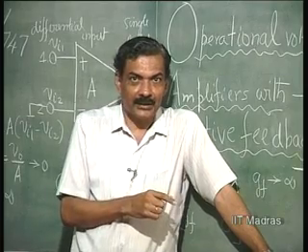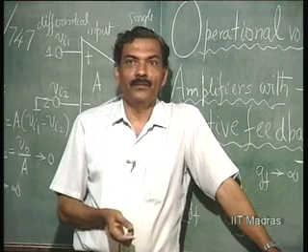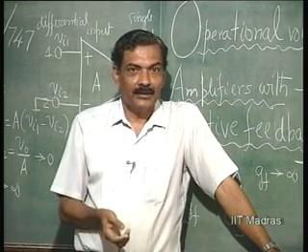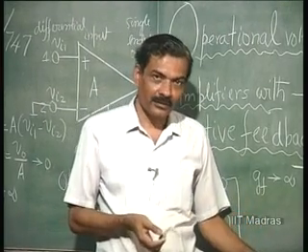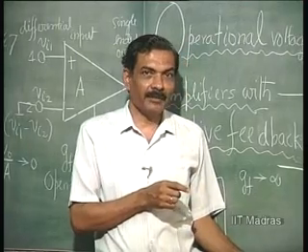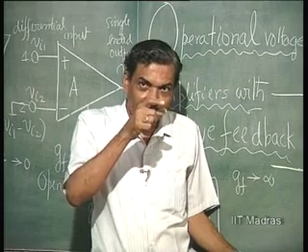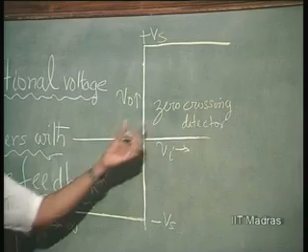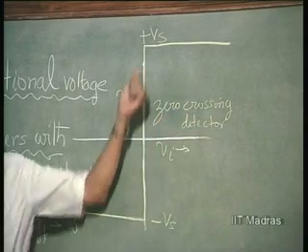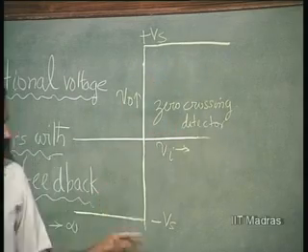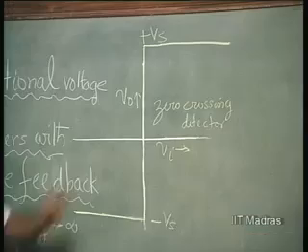If we do not switch this way, then the voltage suddenly rises at that point and it causes a lot of high frequency to be generated. This noise causes a lot of interference all around. In order to suppress this electromagnetic interference, we would like to operate every switch when the voltage is crossing through 0. Now, for that purpose, the electronic device needs a zero crossing detector to tell us exactly when a given voltage is crossing 0. Such ICs are available, and such ICs also use a high gain op amp for the purpose of detecting this 0.